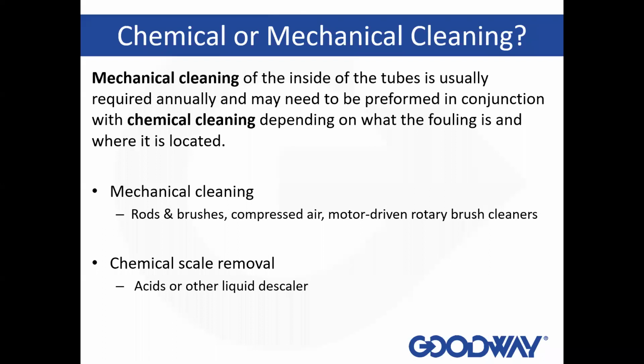You know, a large firetube boiler might be 20 or 25 feet long. And what you need right there is a vacuum that has a high CFM, or moves a significant amount of air. CFM is cubic feet per minute. And what you're looking for is 200 or more cubic feet per minute of air that the vacuum can suck, so that you know it's getting all of those light particulates that are 20 feet away or 25 feet away.